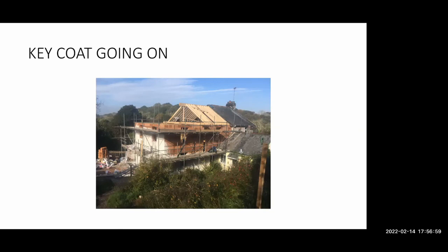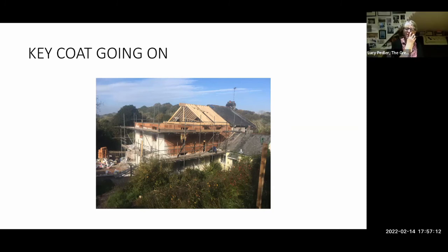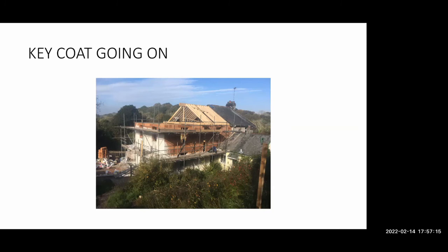And it makes it very easy because you don't have the tremendous fiddle with differential cavity wall construction that we have over here, where your cement block is going one way and your clay brick is going another. Right. The point is very well made. The reason why I never used it in general practice was because it was just so difficult on the smaller projects that we were doing in East London and Essex. But you can use bricks as an external cladding, and in fact they do on the continent, but it has to be thought through extremely carefully at the design stage. And it was an observation really, and like Jenny, I think that if this were to become a mainstream part of the UK industry, the concrete block folks would struggle.